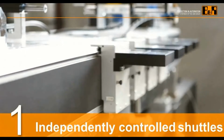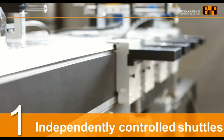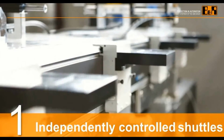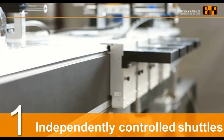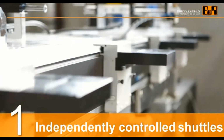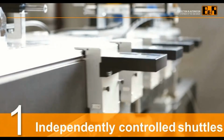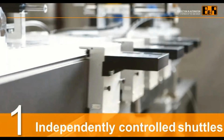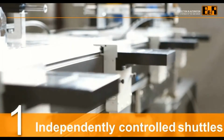So what are some of the features of this track technology that allows it to be so beneficial to production applications and manufacturing? One, like I said, is that every single shuttle can be controlled individually. This means that every product that's on the shuttles can be controlled individually. The processes that they go through can be customized, and you can really have high-speed, efficient production at any batch size, even down to batch size of 1.